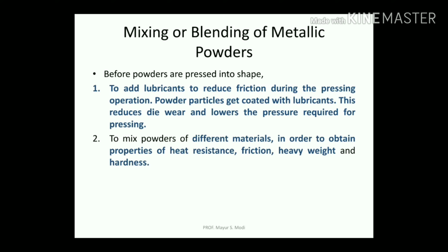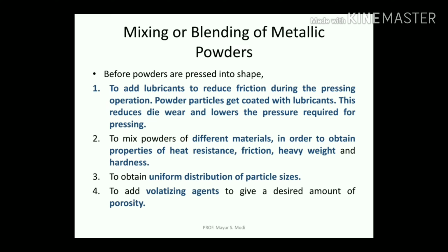Second, to mix powders of different materials in order to obtain properties of heat resistance, friction, heavy weight and hardness. Third, to obtain a uniform distribution of the particle size. Fourth, to add volatilizing agents to give a desired amount of porosity.